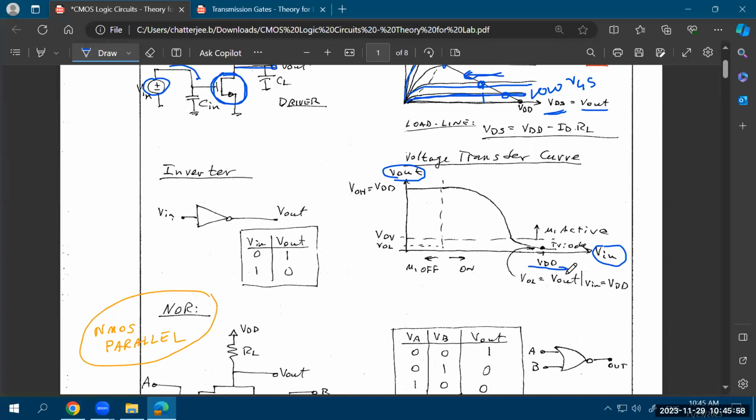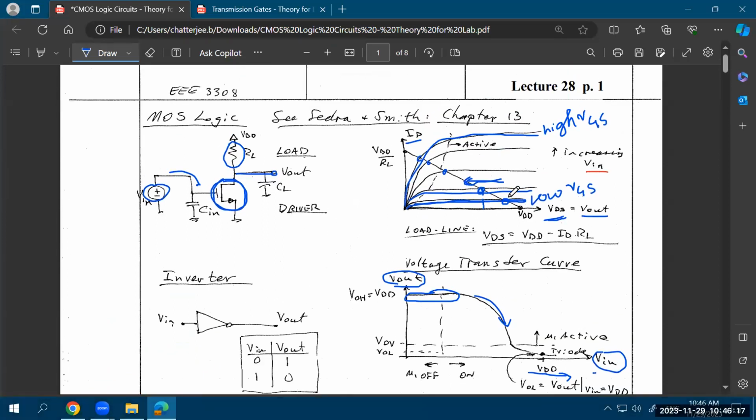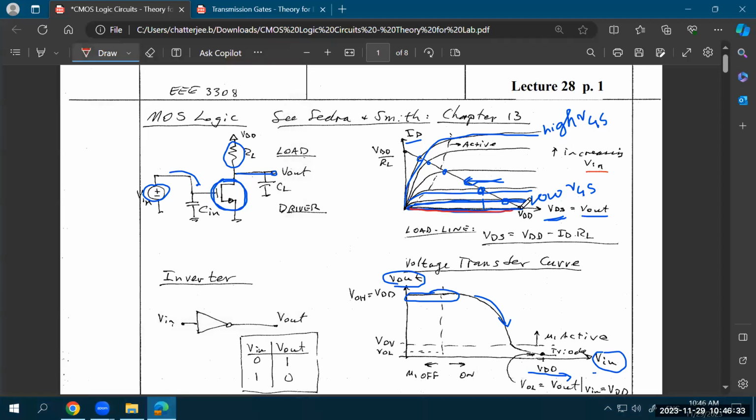That as you increase your V in, your V out reduces, right? So that's another way of understanding the VTC, which is graphically, that as you are increasing your input voltage, your output voltage reduces. Of course, there would be a region when your output voltage does not change over here. That is, you have a VGS so low that you do not have any kind of current flow through the device. So that is basically corresponding to a VGS where your output characteristic is kind of superimposed on top of the x-axis.